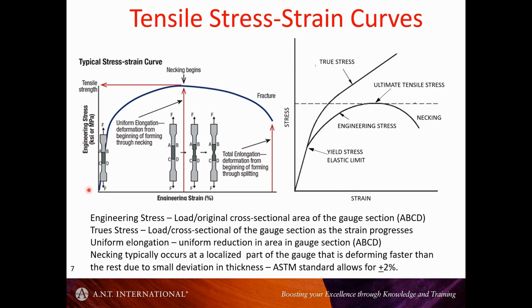If you have a tensile specimen and you put it in a load frame and you extend it, there's a region of deformation which is reasonably well characterized, and that's the period of uniform elongation. This is when the gauge section of the material tends to change.